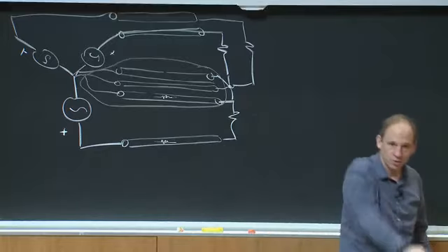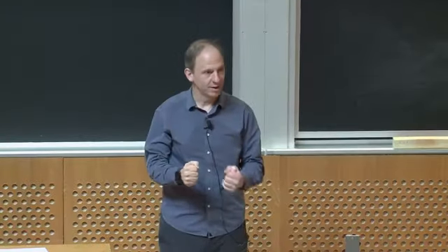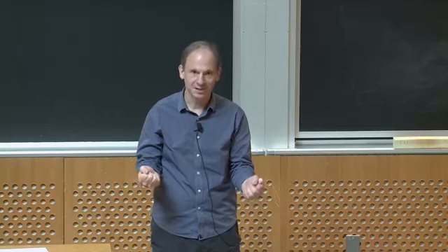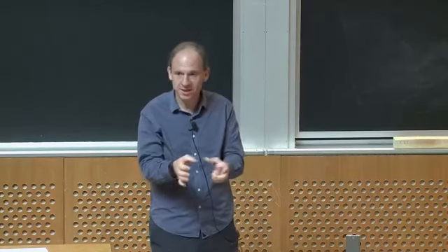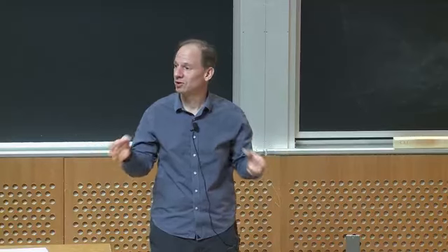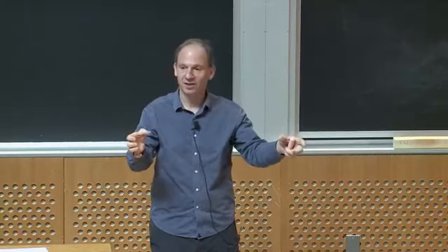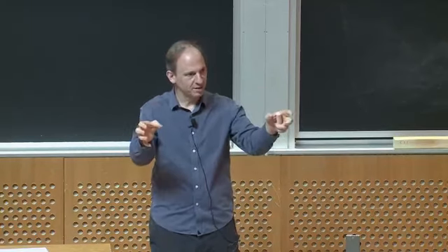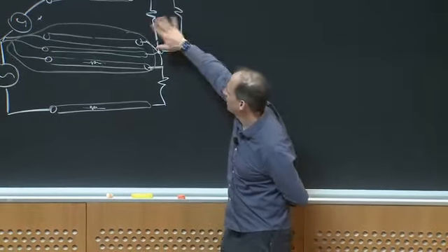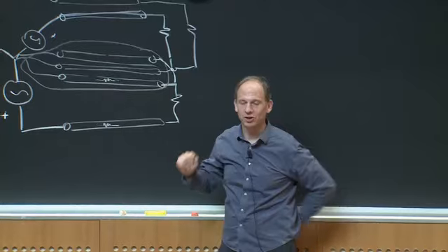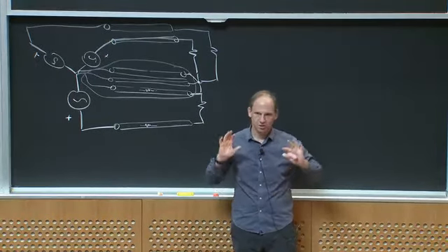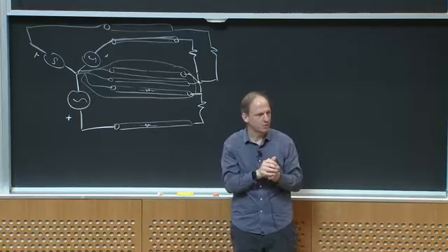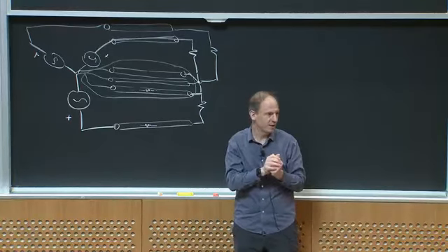That advantage also applies to things like motors, right? So if you wind your motor, you can get away with effectively less copper to do the same thing. It also applies to fluxes and transformers, right? We showed, if you're going to have 3-phase carrying a flux, essentially we're using the other phases to be our return conductors in the same way you can use your other legs in a 3-phase transformer to be your flux returns. Okay? So there's tremendous advantage in reducing the size of equipment by using polyphase.